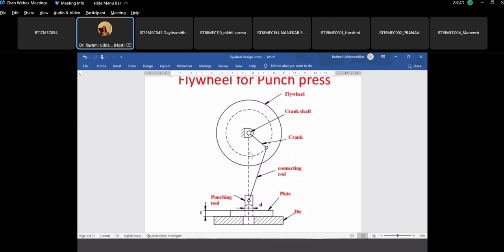So while this is rotating from this part to this part, for 3/4 of the rotation there is no load, and for 1/4 of rotation, when this tool has to cut and shear this plate, this requires a very high amount of torque. And for this torque requirement, the energy required is high, and for the remaining 3/4, when it has to go back, the power required is less.